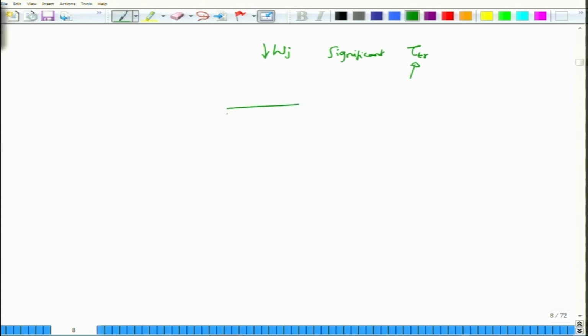But when you make Wj very short, there is also an additional advantage. Decreasing Wj means that a lesser value of V bias is required. So, you do not have to apply say bias voltages of 50-60 volts, you can apply bias voltages of 5 to 10 volts, and that reduces the static power consumption, or rather the voltage requirements of these devices.